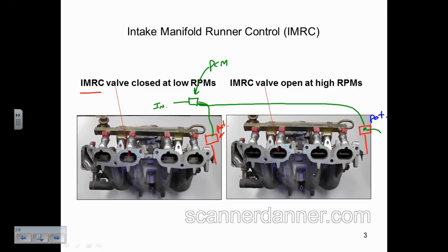Because when the solenoid was turned on, you would be pulling atmospheric air in, and it would never open this one. So this one would stay closed and this one would stay closed. So be aware of that when you check those, because it can be misleading in your diagnosis. Knowing that this is set up like this will help you.